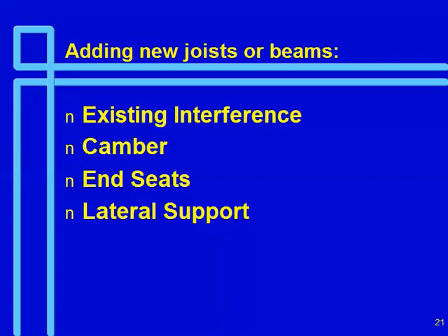And that's normally there by the deck and the deck welds or deck screws or deck pins, whatever you're using. So if you add one now, you got to make sure that you have adequate lateral support for it. And it's not a good idea, you know, to put it in and then shoot nails up vertically, because they'll probably penetrate your roof membrane. So don't do that.